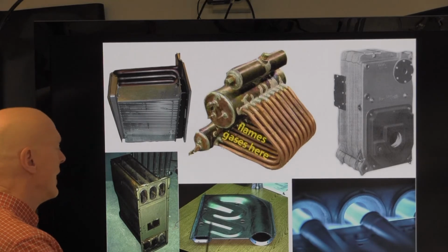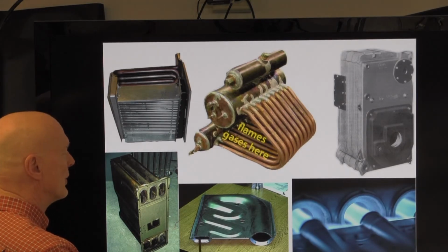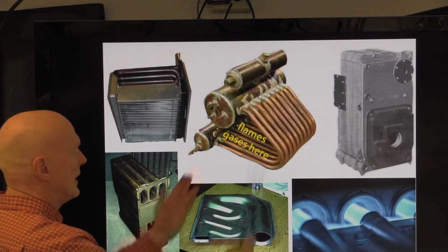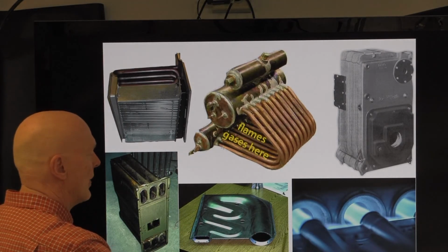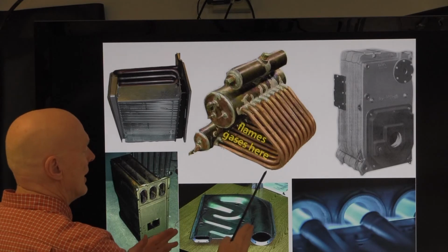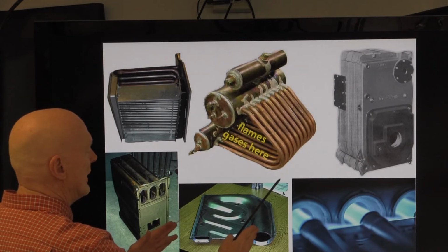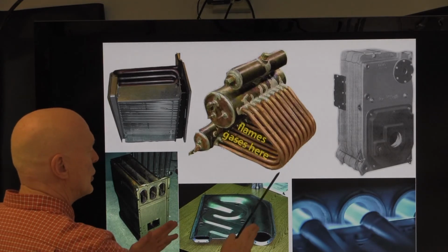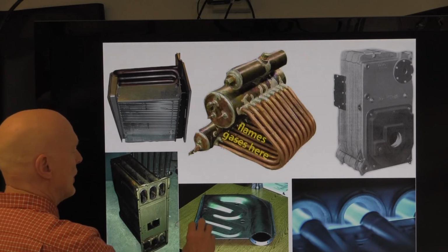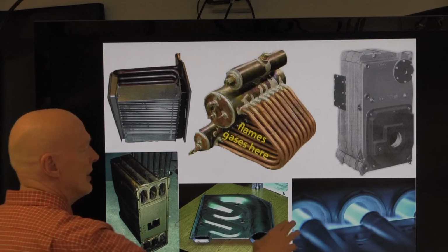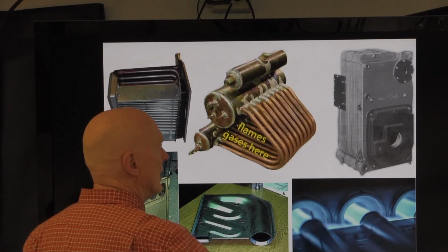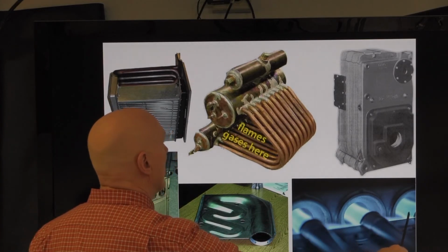And this next heat exchanger is an advancement from that, and it should be tilted this way. You have an in-shot burner like one of these shooting the flame into here. The way it shoots flame in there is that there's a fan connected to here that pulls it in. And you see how these flames are pulled in.